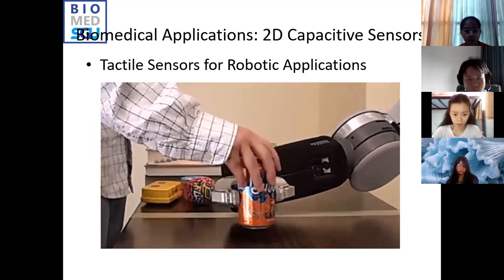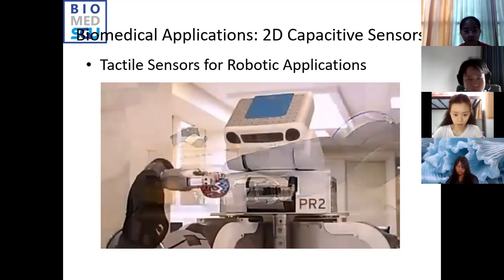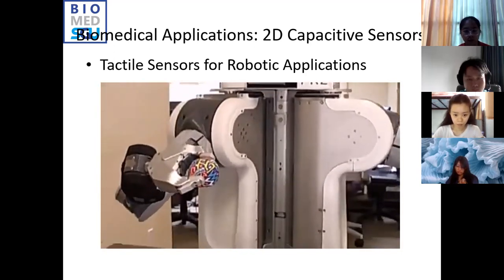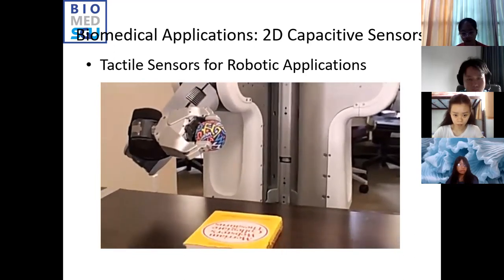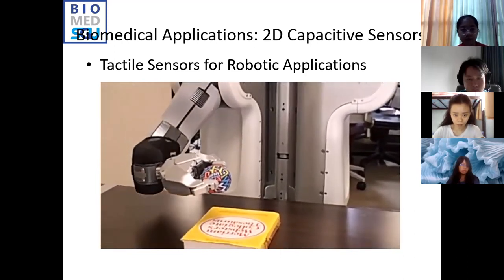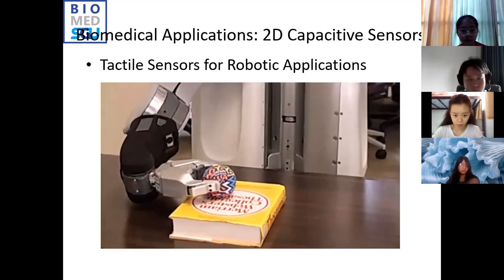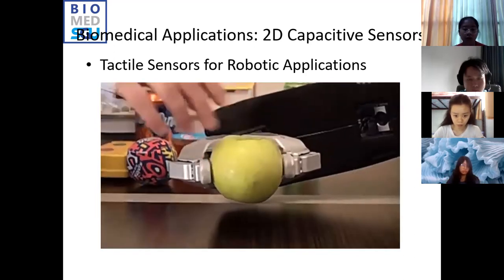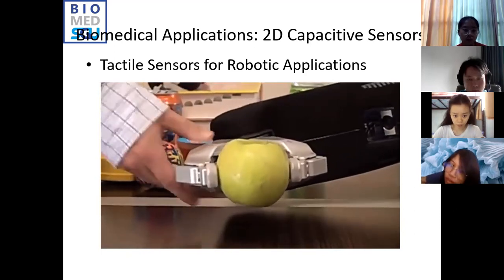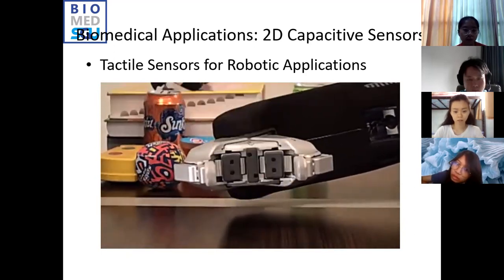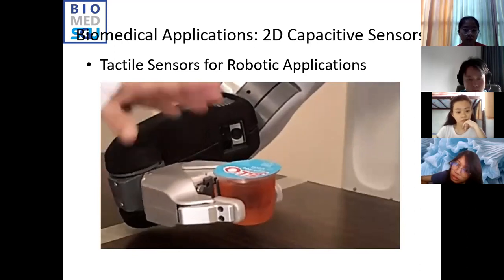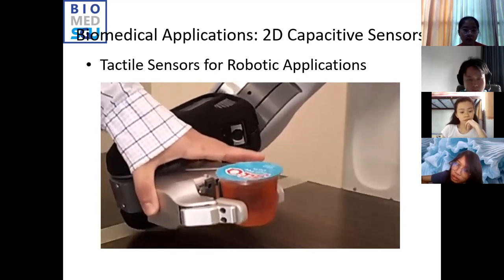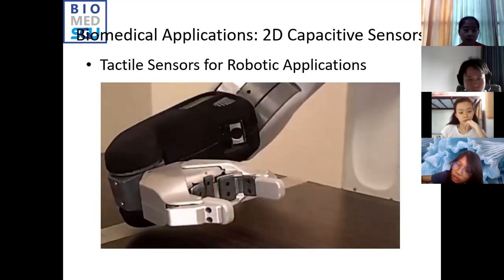During manipulation, the robot detects object slip and increases the grip force to stabilize the grasp. When placing objects down, the robot detects contact with the table through its tactile sensors and gently stops its motion and releases the object. We have found that tactile information also plays a useful role in handing objects to a human. When the robot has decided to hand over an object, it is able to detect when the object is being pulled from its grasp, a natural signal to release the object.